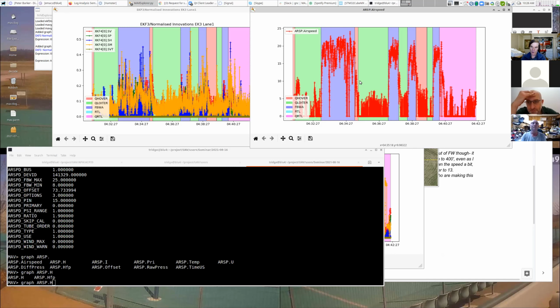We've got a bug. So this plane runs Q assist permanently, right? Because in fixed wing flight here in this fly-by-wire A mode, it's flying in forward flight, but it's running the quadcopter control loops to control it in forward flight. Yeah. And we set that flag based upon whether the VTOL motors are active on a quad plane, which means it always doesn't think it's forward flight. Now that's going to ruin our side slip fusion. You won't have side slip fusion running at all. That's right. So that actually means this log has found two bugs.